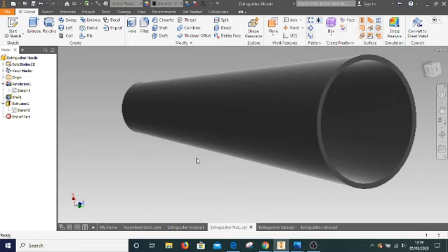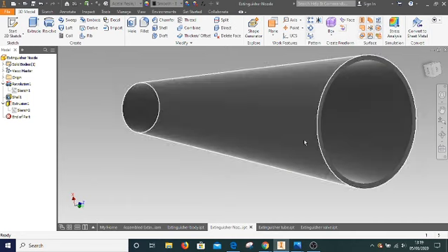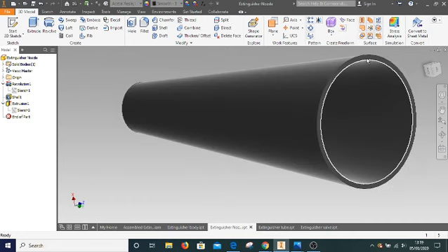Once again, I could have done it through lofting. I could also have sketched the profile, which would have taken into account the wall thickness before I revolved it. So like most of these tasks, there's more than one way to do it.